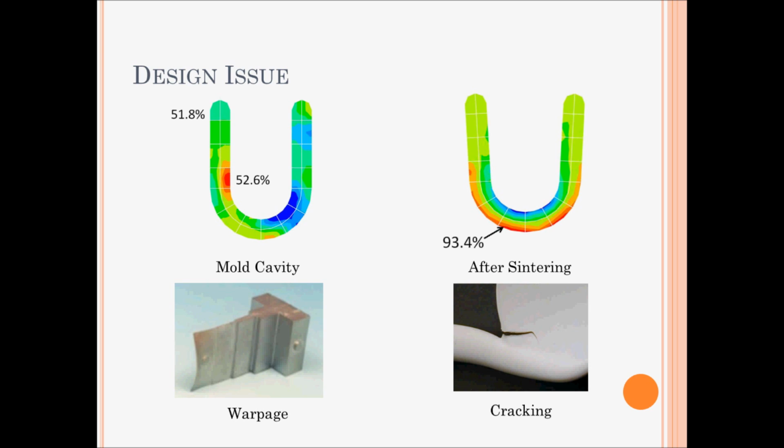Obviously, you want to design against short shot, flashing, and other common defects in the molding process, but also be cautious on the gate location.